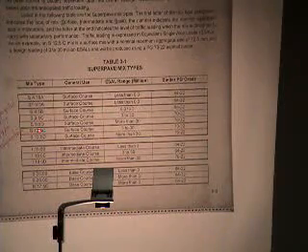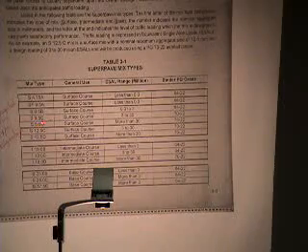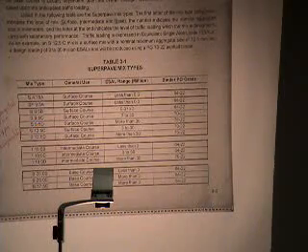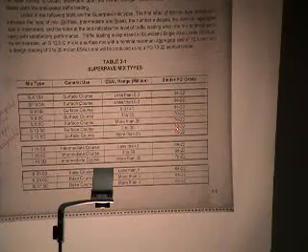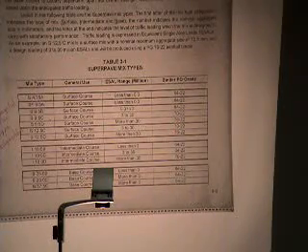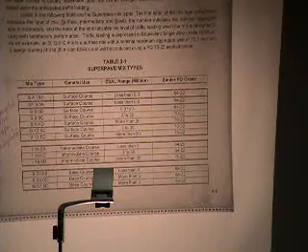You get to the real heavy traffic situations like on a 9.5D and a 12.5D, we bump up to a PG76 grade, which is a very stiff asphalt. It provides a lot of rut resistance.